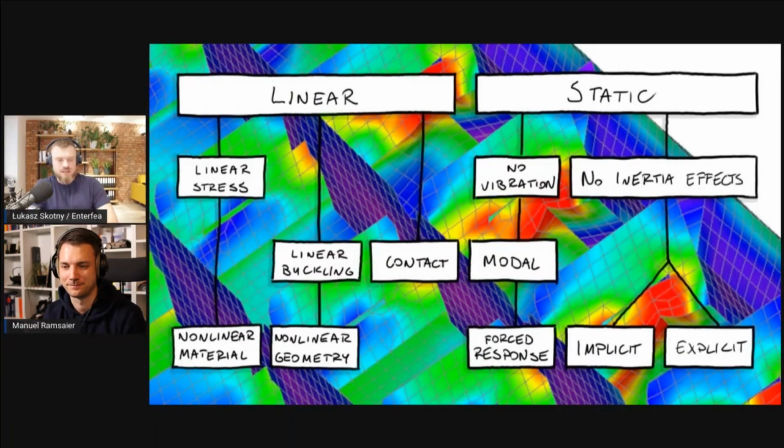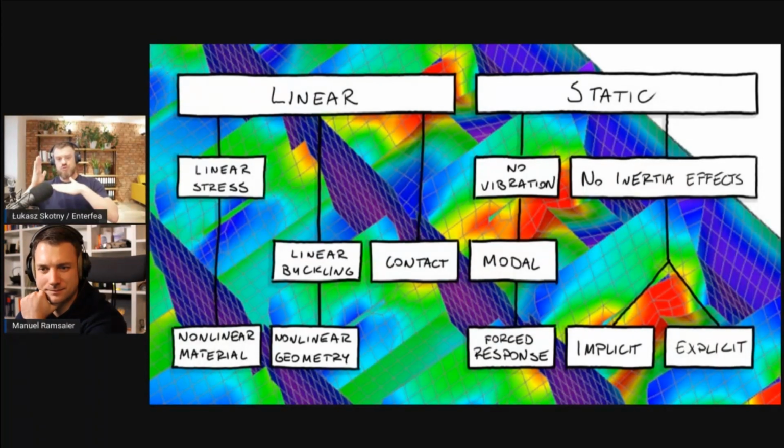To me, as a structural engineer, contact is not a very complicated thing. Because you can have friction or not. In a very basic scenario, you can have kinetic friction. If you want to see how much force you need to start pushing something and then push it along, starting is more difficult because you have static friction, and then pushing it along is easier because of kinetic friction. That would be as complex as you can get.